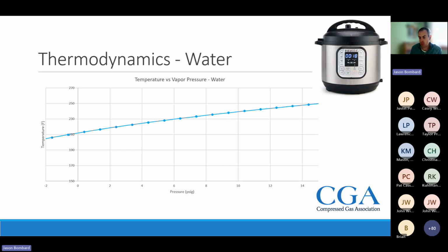done cooking, you've got two options. You can typically let the pressure release itself, which means that you're waiting for it to cool all the way back down to 210, where it gets to 0 psi. Or if you release it instantly, you open that valve, all that steam hisses out, and if you pull the lid off quickly enough, you'll see that liquid's still boiling inside it. It's because it's still up in the 240-degree range. It'll keep boiling until it comes back down to the 212.